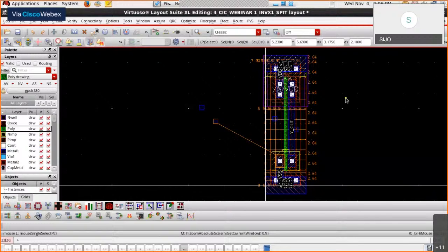So in 180 you can see the same. 1 poly 6 metal means you have 1 poly and 6 metal layers. So metal 6 is the top metal. How that hierarchy goes, the foundry will give the information. So if you look at real foundry files, you can find all this information.